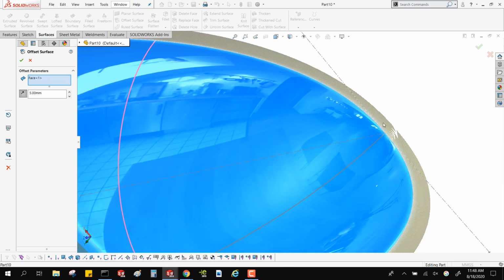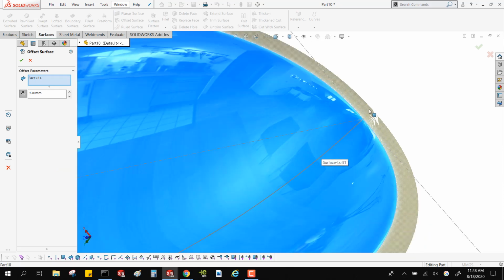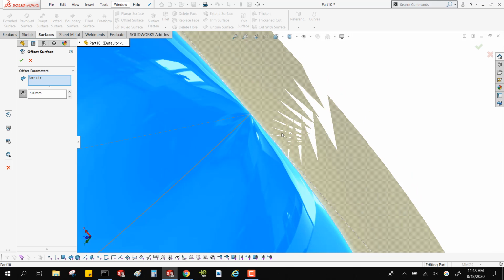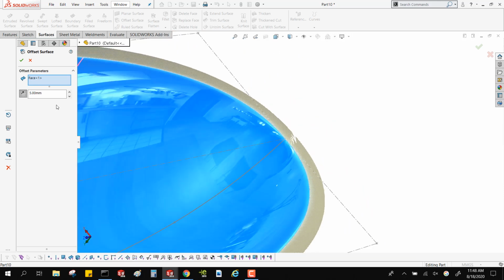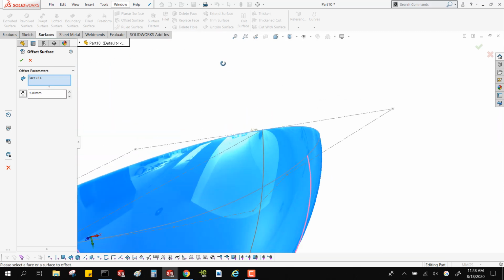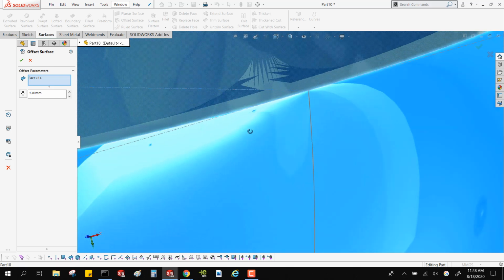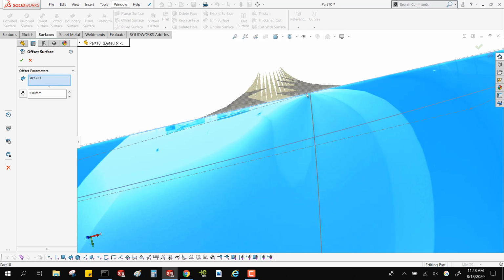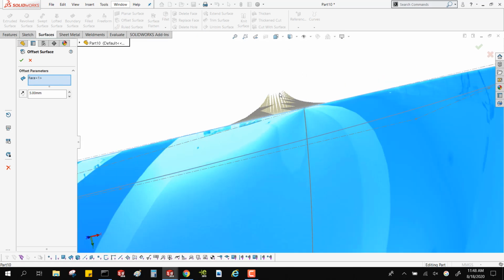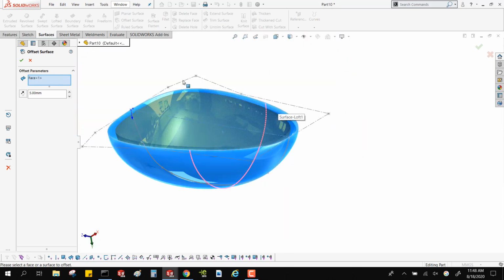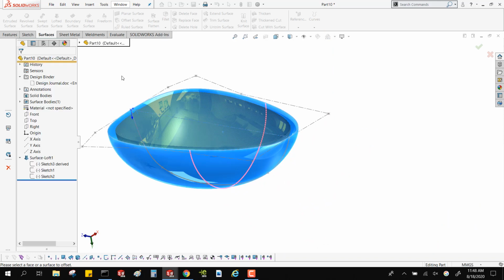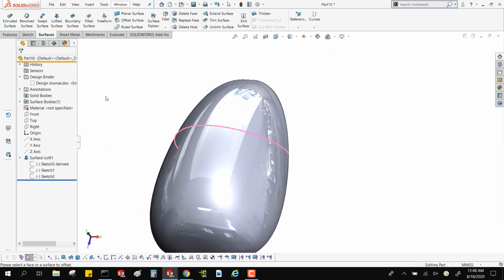It gives you some sort of error like, bad geometry. It doesn't really give you much of a clue as to what's happening, but this is what's happening. I can't thicken this thing to the outside because it's going to start to fall apart there. I can't do it to the inside either because it starts doing this. Because it says, okay, this point is offset there, and it's just terrible. So, okay, that's what a three-sided surface is and why it could be a problem later.